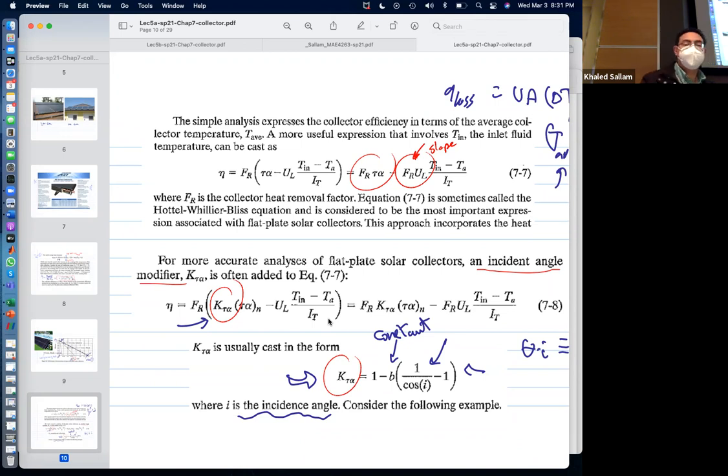For this particular day, calculate the angle on the plate, or the collector, and from that calculate K, and from that calculate the efficiency. You can see the ambient temperature also, and Tn, so you can calculate the efficiency throughout the day. And then you will figure out when the solar heating was not enough, and we will have to turn on the electric heater. And we'll have to fix the load.